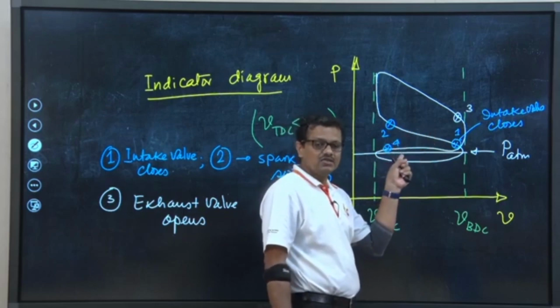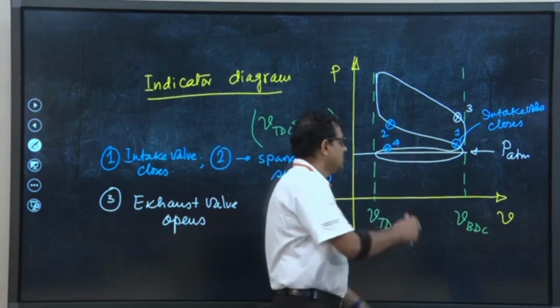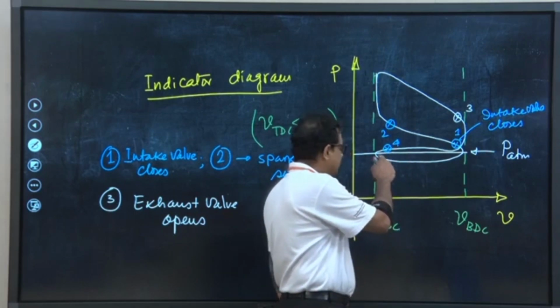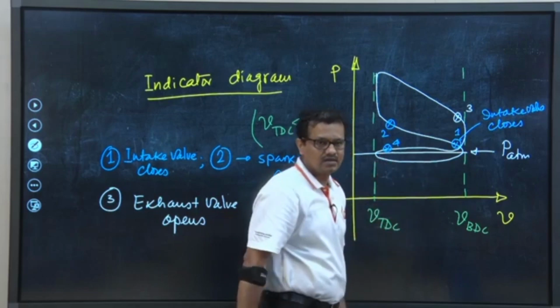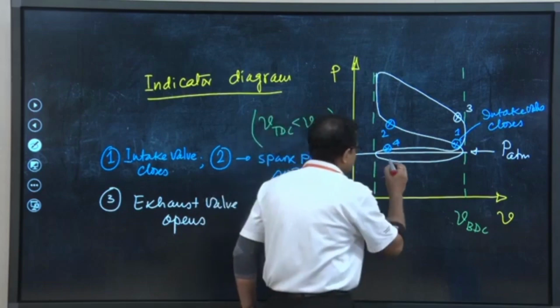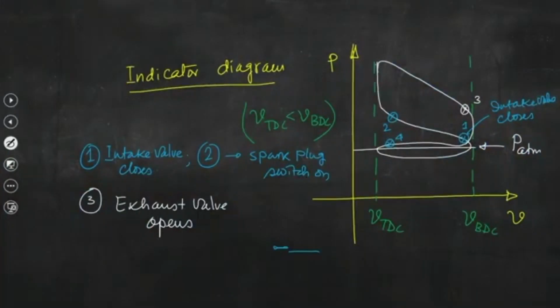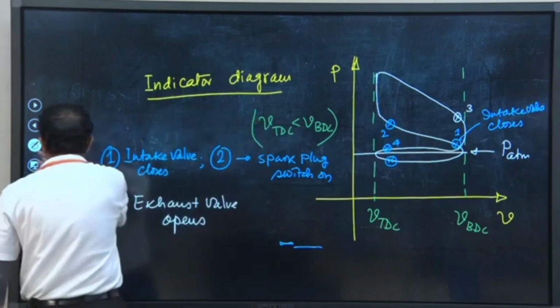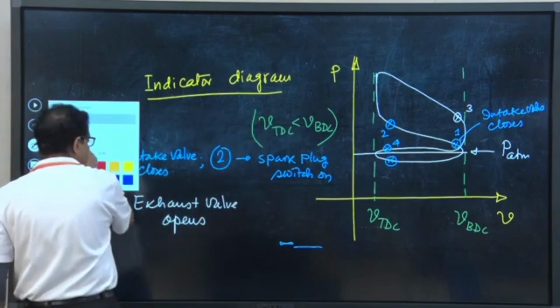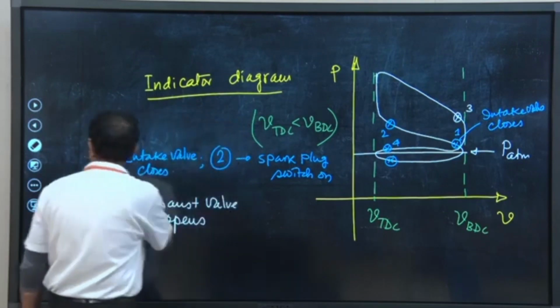That is why the exhaust valve remains open until the piston is again travelling back from TDC to BDC during the next cycle intake stroke. So, the exhaust valve is allowed to close when the piston is a little away from TDC during the next cycle intake stroke. So, try to understand, which is really interesting, that